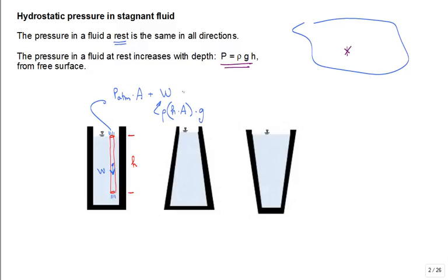All right. Those are acting down, and then the pressure at that depth times the area acting up. We cancel the areas. And if you say, hey, I'm interested in the gauge pressure, then the pressure is equal to rho g h. Let's say I want the absolute pressure, well then I have to add the atmospheric pressure on the top of that fluid column. Rho g h. Rho g h. Did I encourage you?